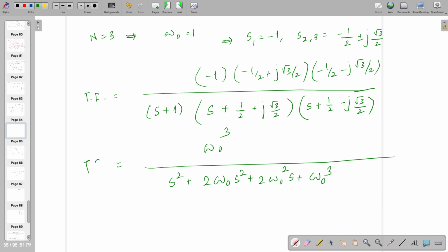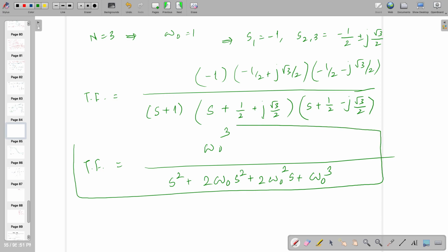So this is the generalized equation for a third order system, right? So now can you draw the circuit using op amp, because that might be the last answer, right? And can you scale them with the omega 0 value? Let's assume that omega 0 is equal to 1. So now can you design a circuit using op amp?